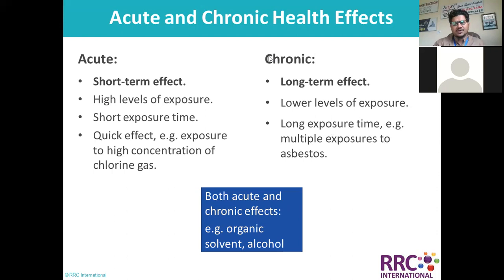And I hope you remember I shared one of the stories of how asbestos fiber can kill the people who are working in the textile industry, cement industry, and construction even, especially for sealing work, especially for coating of certain pipes, or renovation projects. When we accept any project for renovation of any existing building, then asbestos-containing material must be evaluated. Otherwise, once those fibers go into our lungs, there is no way to get them out. So in the short term, you might not face so many consequences, but in the long term, it's a kind of lung cancer.